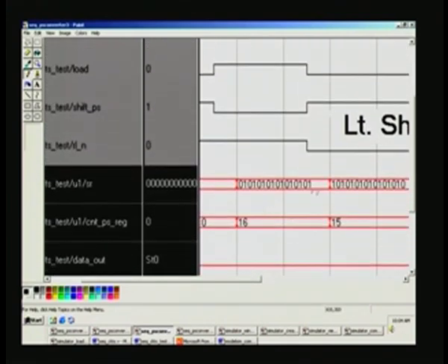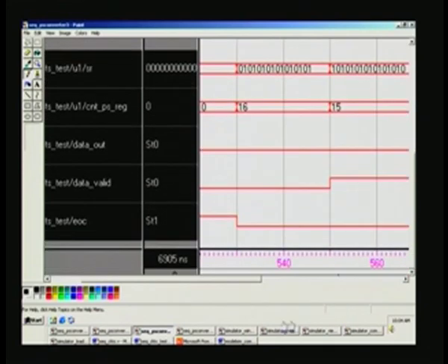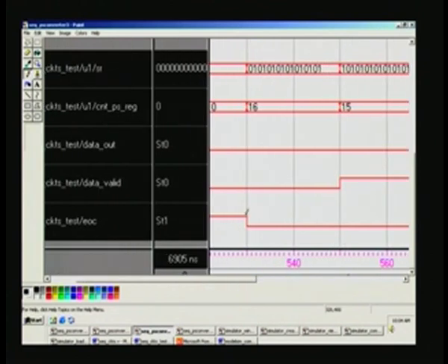So, you can see same 0 1 0 pattern here, and once again this end of conversion, this is the previous end of conversion which we had processed. So, the moment you load a fresh data, that is reset. So, you will have to take care of all intricate details while designing systems, and data valid was deasserted in the earlier cycle. So, it will have to be asserted here the moment data starts flowing out, and once again the parallel to